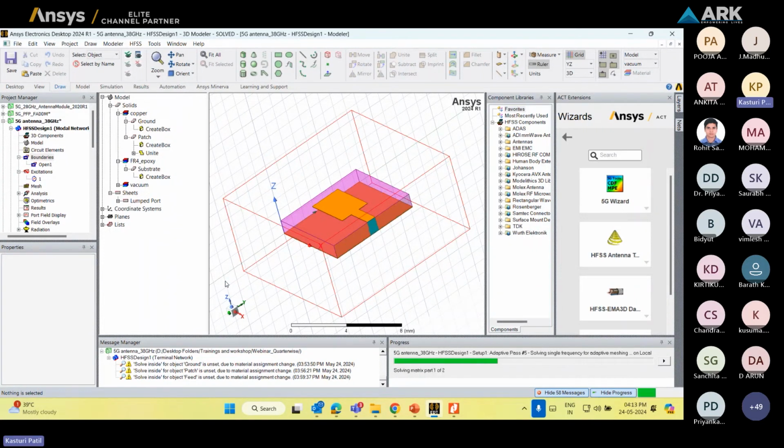Now in case of an array using the domain decomposition method, as we know, the finite array wizard assumes that each element in the array is physically the same with the same field pattern, and in case of an array uniformly excited in magnitude. In case of HFSS, we can give phase shift here. That unit cell needs to have coupled boundary conditions, that I'll explain once the simulation is over. We'll see these results and we will move to the array design using the domain decomposition method.